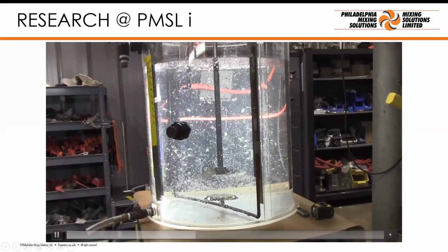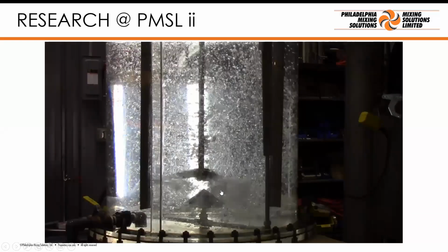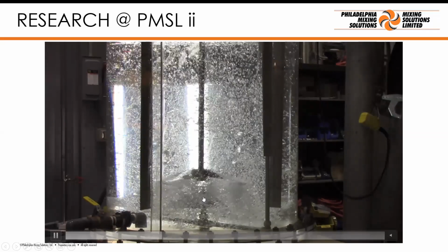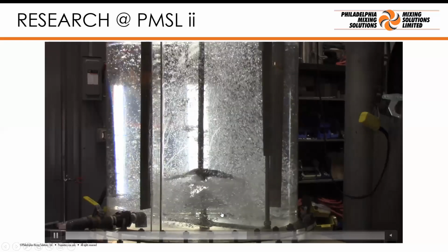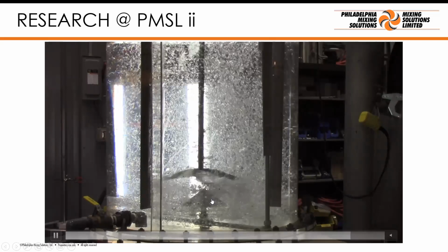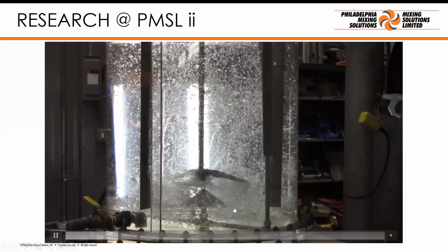So this is a flat plate. And this is a cone. So the gas is coming in inside the cone, coming out, being dispersed. But if the agitator turns off and the solids settle, we won't block the gas pipe. They'll be kept out by the cap.